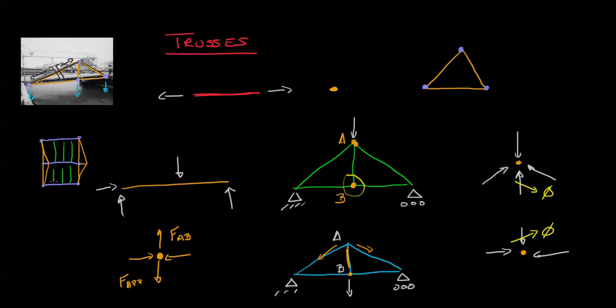And then what happens is as your truck moves across, it's going to move its weight more and more from this member. Halfway through, it's balanced between these two. And then as it gets closer to this stringer, this force is going to decrease, and it's going to move its force all the way across. The important thing being that it's going to apply that force at each of the pins.